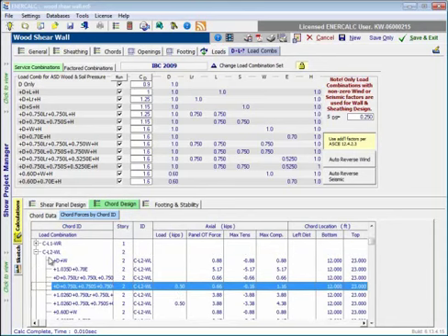So at level 2, the chord that's at the left edge of the wall, for a particular load combination here, we can see that we do have an applied load. This would be due to either applied uniformly distributed loads or concentrated loads or loads from above. But we have a 0.5 kip load on this particular chord member. The next column over reports the panel overturning force. So there is potentially some overturning moment in this panel which can be coupled out by the distance between its chords and resolved into a compressive or tensile force, and that's what this magnitude is.